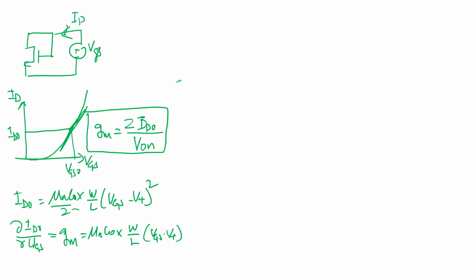Fixed current we are biasing at, and we have a limit on the current, and this is the headroom. Remember yesterday when you were sweeping, the current mirror is only valid after a certain VDS, which was equal to this value, right? So if I'm designing an amplifier, I say, your output cannot go lower than that because that thing collapses, right? So that number is a useful number for us, and ID is because we are usually given a certain amount of power we can dissipate.